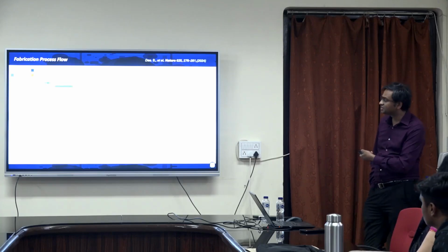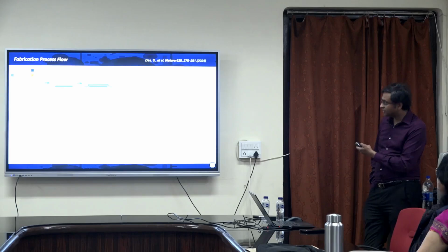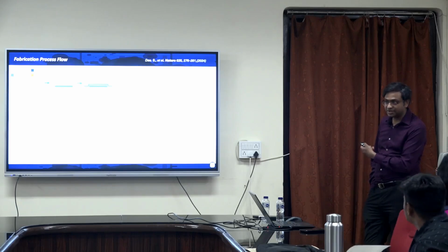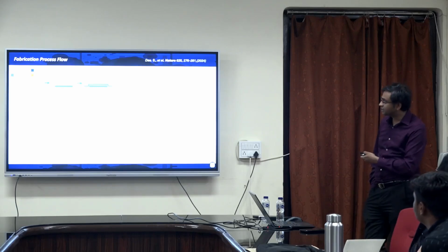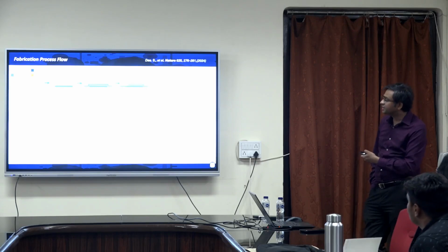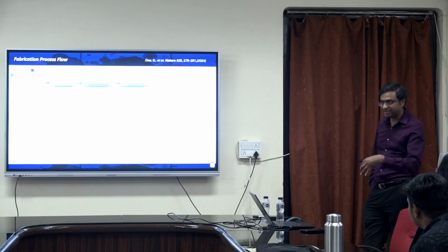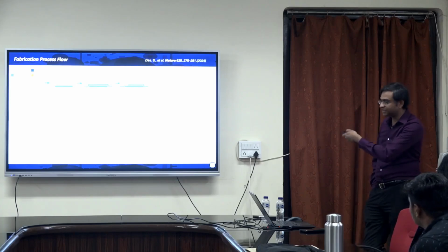So first we do this tier 1 gate. First we do the gate, then we transfer, then we do the gate oxide, which is our floating gate. Remember, this is what we want to integrate memory and logic. So we do this alumina, hafnia, alumina. Then we do an etching process, which also will require us to do an E-beam lithography to define the pattern, then go and etch it, right? So an E-beam is involved with the etching.